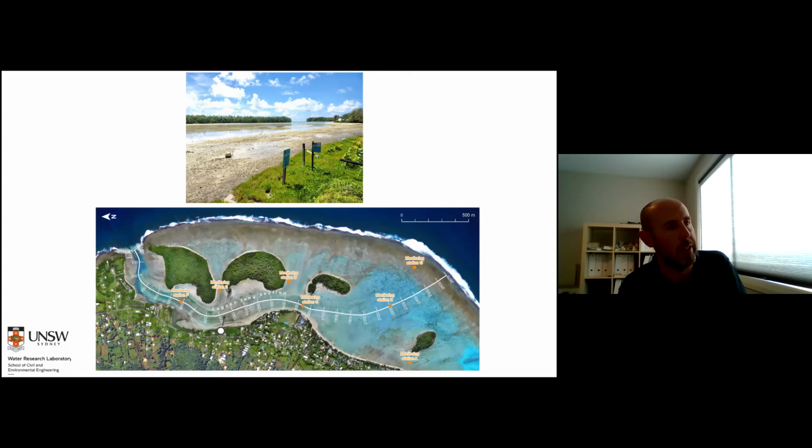That happens to be at the exact same elevation where water level stopped draining. Way back at the start, I said that once the water level in the lagoon got to about 0.1 meter mean sea level, it stopped draining. At that point, this ridge was becoming dry. So this feature really holds back the water in the lagoon once you get to that point in the tide cycle. That was something that hadn't really been mapped out in the previous studies.